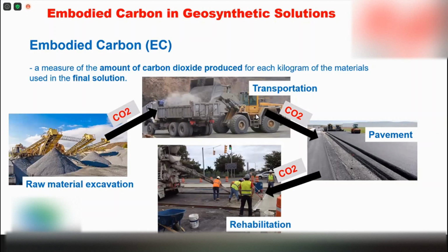Now, how does it manage to do that? Why this geogrid is different from others is because of the triangular grid. Having this triangular grid, it's not just acting as a reinforcement, it's actually acting as a net to capture all the granular material together to prevent them from moving when the load is running on top.